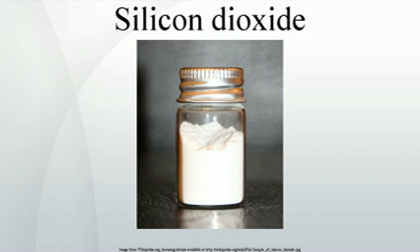The high-temperature minerals, cristobalite and tridymite, have both a lower density and index of refraction than quartz. Since the composition is identical, the reason for the discrepancies must be in the increased spacing in the high-temperature minerals. As is common with many substances, the higher the temperature the farther apart the atoms due to the increased vibration energy. The high-pressure minerals, keatite, stishovite, and coesite, on the other hand, have a higher density and index of refraction when compared to quartz. This is probably due to the intense compression of the atoms that must occur during their formation, resulting in a more condensed structure.